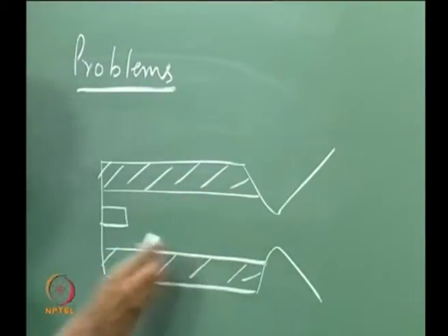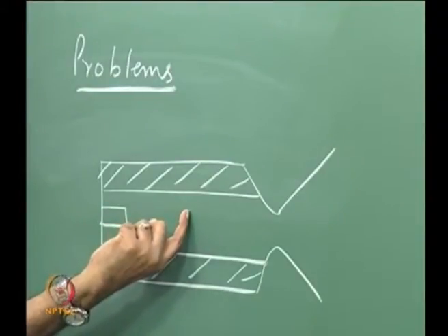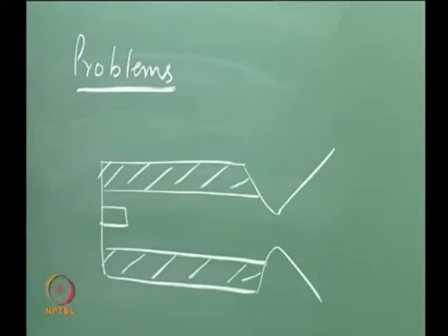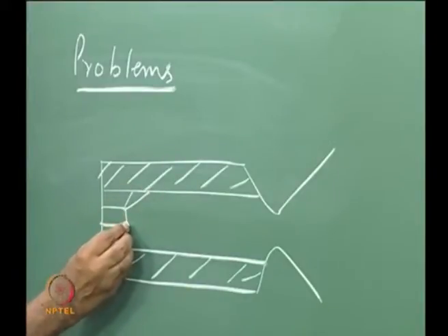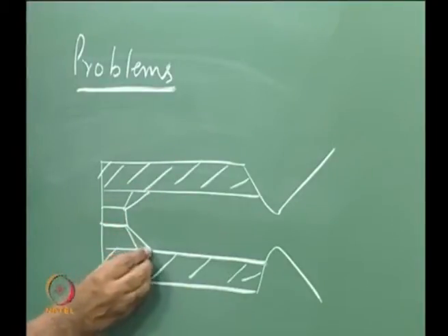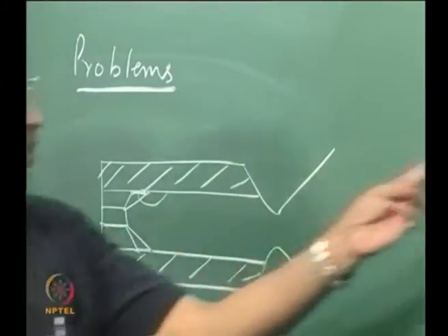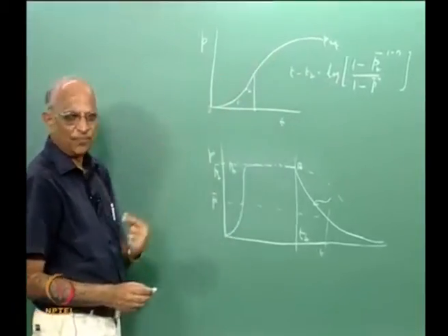Now I make an igniter, and how do we design an igniter? We were very clear, it must pressurize this cavity to some not very high value, such that a flame can be near the surface, and also give some energy, since propellant requires some minimum energy for ignition. I get some plumes and it ignites a particular surface. This is all the requirement, and thereafter the flame spread and pressurization takes place, and we had this particular curve: local ignition, flame spread and pressurization.